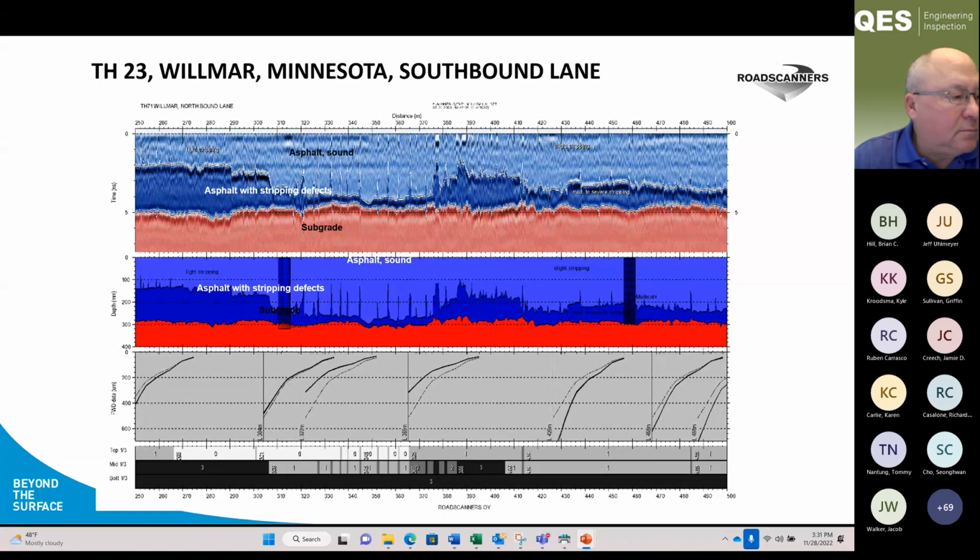For instance, falling weight deflection bowls are not like typical round deflection bowls, but they have strange curvatures and look a little bit strange, and by analyzing that you will always get an indication if you have severe stripping. And next slide.